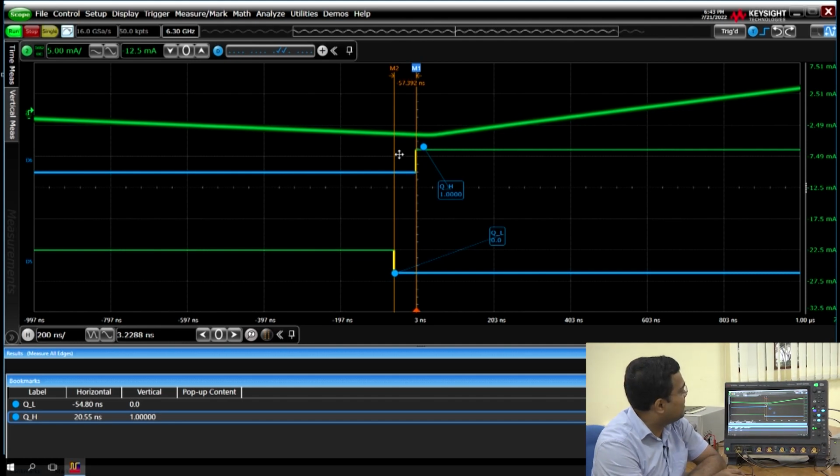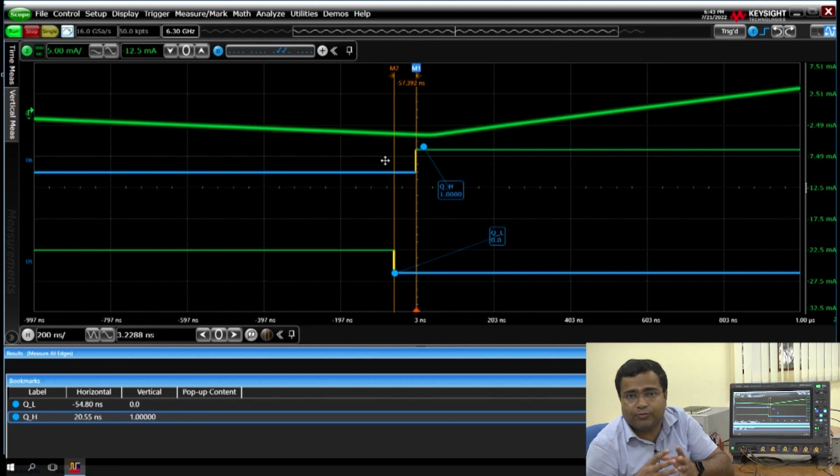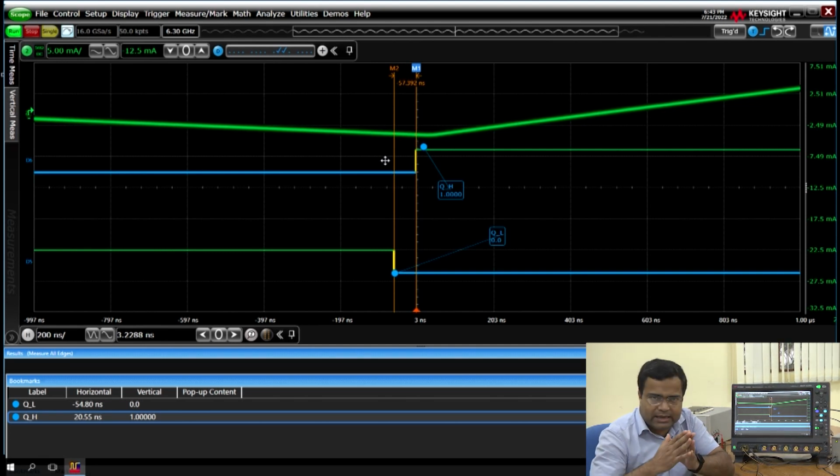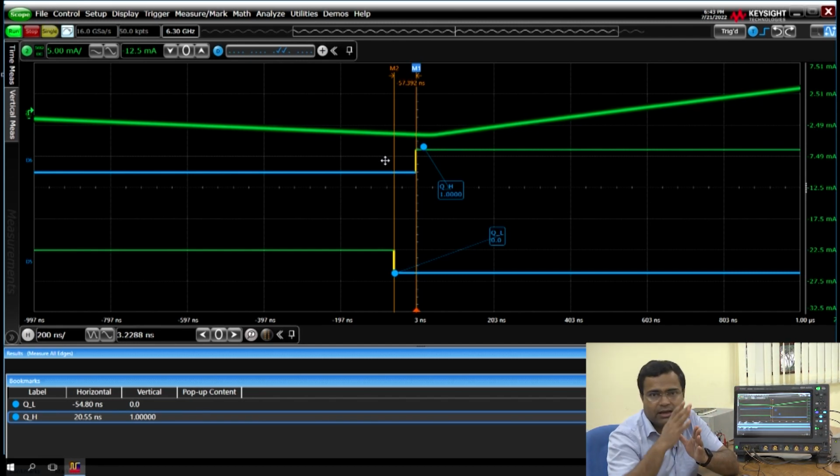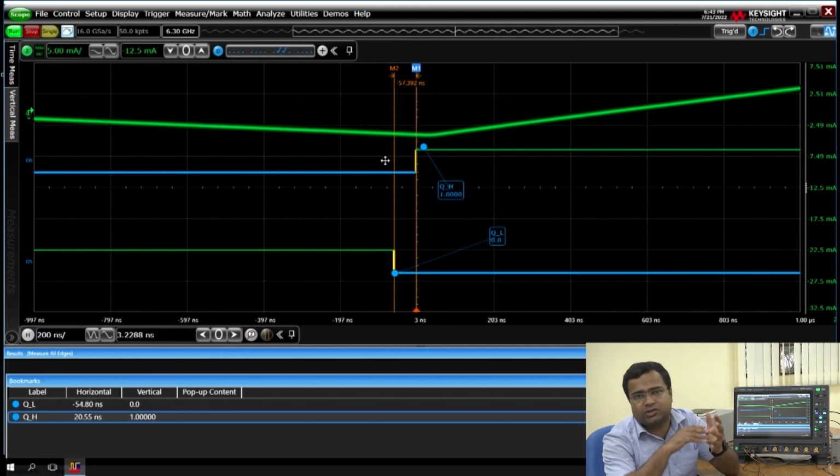But this dead time amount is in the order of a few tenths of a nanosecond, around 40 nanosecond, but you can increase that. If you decrease the dead time, what will happen? Because the switches have some finite slew rate, rise time and fall time. If you decrease the dead time, there can be a situation when both the high side and low side MOSFET can be on, and that can short the ground and it can have a huge inrush current.